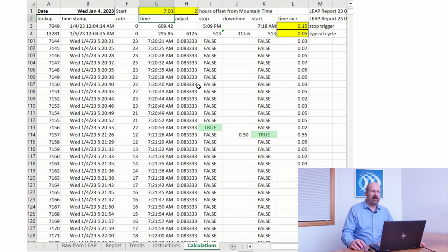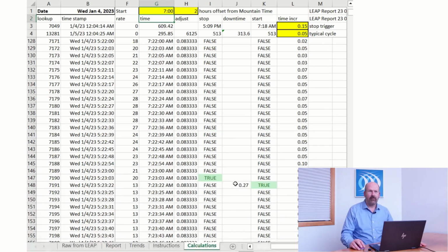So where did this data come from? Well, looking at the data, I came up with simple formulas that determine if a data point indicated a stop, a start, ongoing running time, or an ongoing stop. I allowed a little variance for communication time, so we can accurately tell when too much time has passed between stamps for counts. So for example, if 30 seconds passes between one count and the next, we can be confident the line was down during that time.